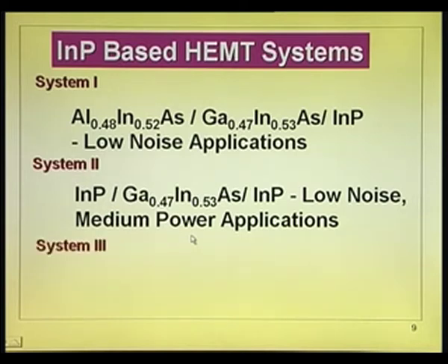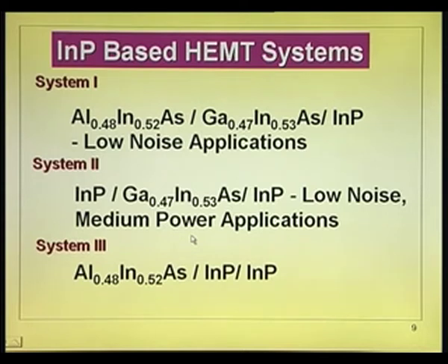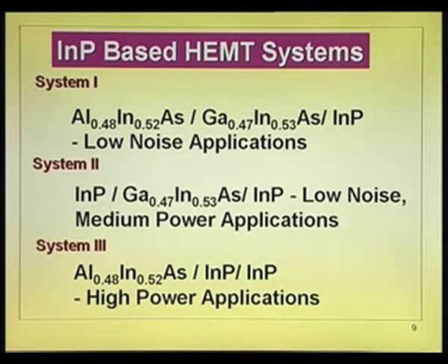No. System 3, throw away indium gallium arsenide. It is only for high power applications. That is, do not use indium gallium arsenide, keep that top layer, put this indium phosphide layer. This material has a wider band gap compared to gallium indium arsenide, 1.35.